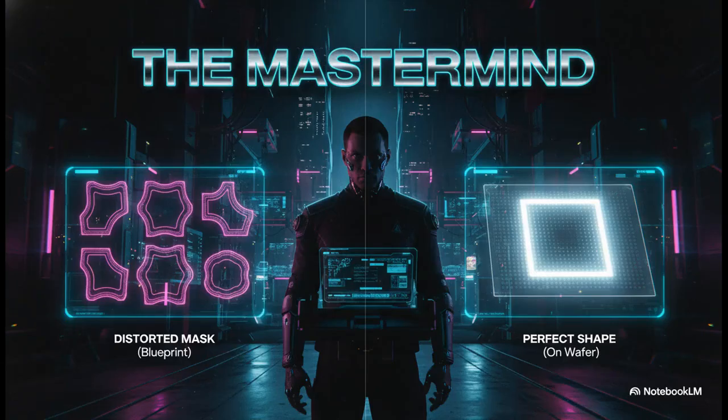Okay, next up is mask optimization. And this is where things get really clever. If the system knows that the light is going to bend the corners of a square, what does it do? It changes the blueprint. It actually designs a mask with these bizarre, distorted shapes that look nothing like the final pattern. But, and this is the genius part, they're precisely calculated so that when the light inevitably bends them, they land on the wafer as perfect squares. It's like writing a distorted message that only a funhouse mirror can read correctly.